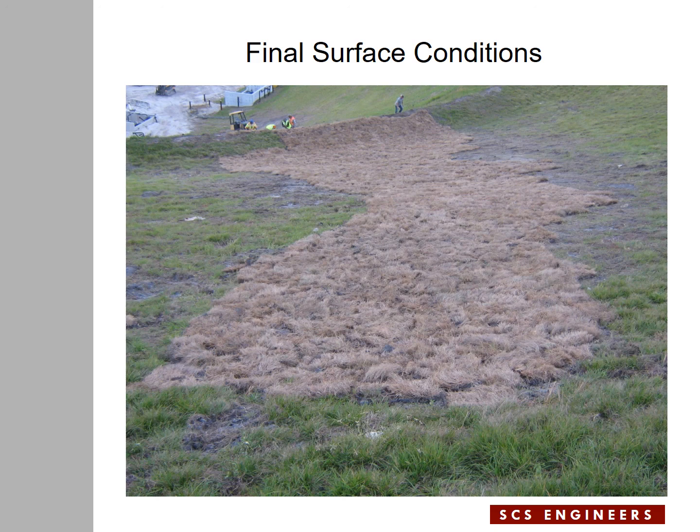Again, we are not saying that this is the only way to address the issue, but we are recommending that the designer evaluate the concave surfaces and devise measures in the final cover system ahead of time, before construction, to address the convergence of water in the composite.